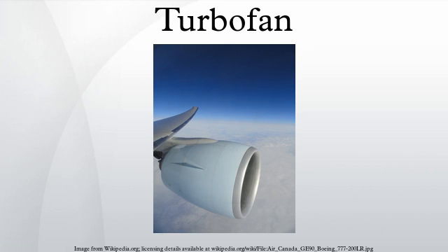Otherwise, a two-spool turbojet is much like a single-spool engine. Modern turbofans evolved from the two-spool axial flow turbojet engine, essentially by increasing the relative size of the low-pressure compressor to the point where some of the air exiting the unit actually bypasses the core stream passing through the main combustor. Civil aviation high-bypass turbofans usually have a single large fan disc, whereas most military aviation low-bypass turbofans have multi-disc compressors as a compromise between greater power-to-weight ratios, supersonic performance, and the capability of using afterburners, versus the higher fuel economy of a high-bypass design.